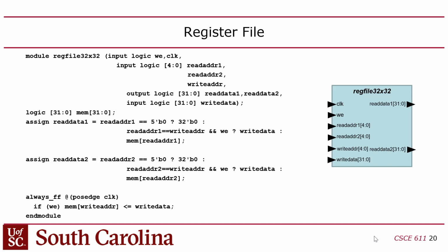Now, why do we do that? I actually forgot. I think the reason is so we could move branch resolution up as early as possible. If you make the register file asynchronous, you can read the registers and then do something with them in one cycle. If they were synchronous, you wouldn't be able to use the registers in the same cycle that you read them.